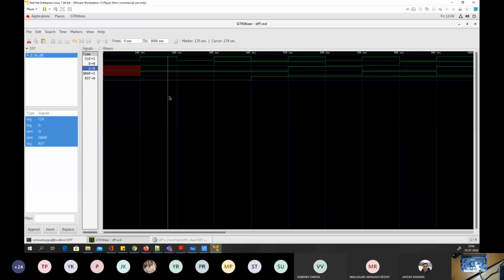Of course, here, as I said before, it's still valid, but we should have a justification for why we have these red signals. In most tools, red is a problem, x, which means we do not know whether it's a 1 or 0. So now you tell me, why do you think we have q equal to x? I can simply tell you the answer, but I want to give you some time to think.